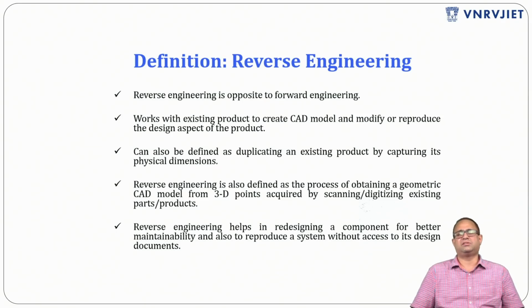Reverse engineering, I can say, is simply opposite to forward engineering. Suppose the CAD model is not there, and the concerned company wants to upgrade their old model. If the CAD designs do not exist, then there is a role for reverse engineering. Instead of doing the CAD modeling, the old part is going to be scanned, including the outside features and the inside features. Then that data is obtained and processed in the reverse engineering software.